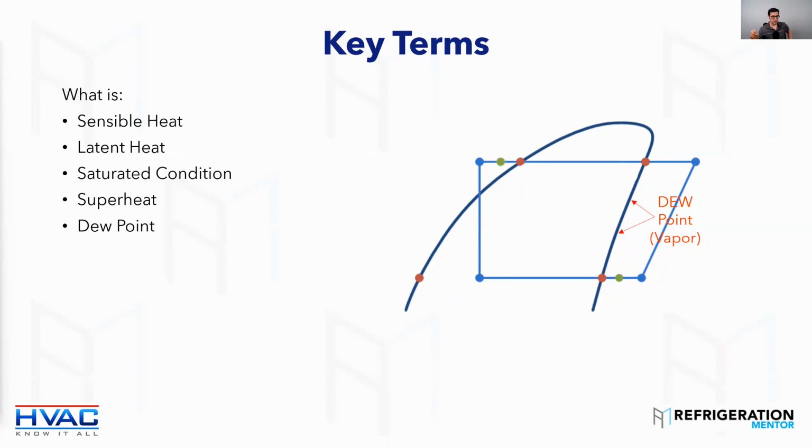And Brett puts it in the chat: Dew, superheat, and bub, subcool. So that's one way to look at it. But just remember that anytime you're checking superheat, you always use the vapor point or the dew point. And it depends on the PT chart you use. I guess you're all probably using apps now, which makes it a bit easier.